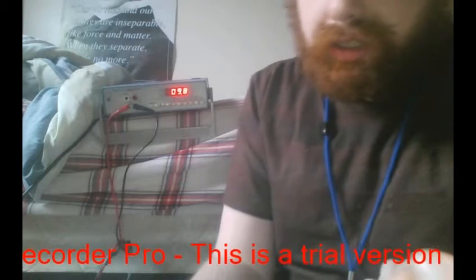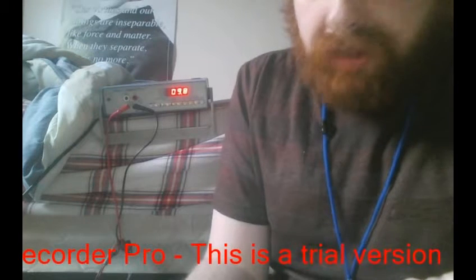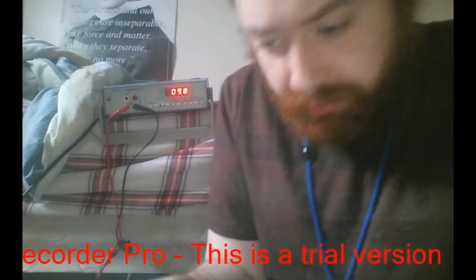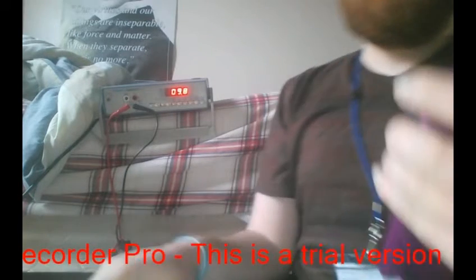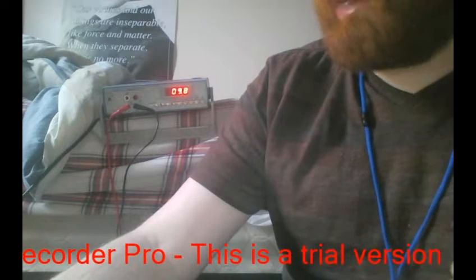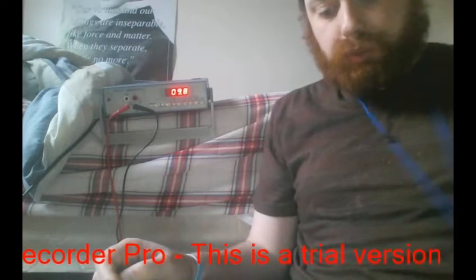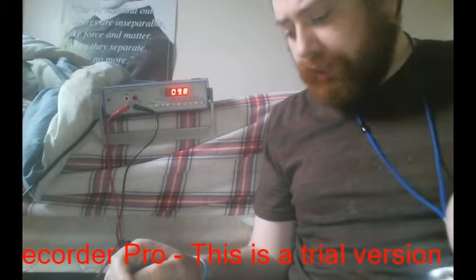This is a great way to measure it, though. If you have an AC current meter, you can do this. You want to get one that goes down to the lowest current range you can, because those capacitors are not going to source very much current through them, because of the small capacitance that you're measuring.